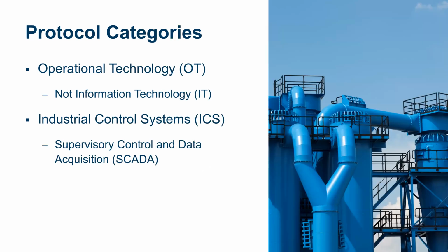So I mentioned a couple of different words, SCADA, ICS. It's useful to explain what those mean, just so that you can have more meaningful conversations down the road, right? So operational technology, we're all familiar with this because of the plethora of IoT devices out there. You have your Internet of Things all talking out on the internet and doing various interactions with the physical world. And that physical interaction is what makes something an operational technology as opposed to an information technology. Your information technology, your IT stuff is servers. You have a computer talking to another computer, putting data into a database, displaying something on a screen, but not typically turning lights on and off, not typically turning a process on or off. So that's the distinction between OT and IT, is that in operational technology, you're interacting with the physical world in a real way.